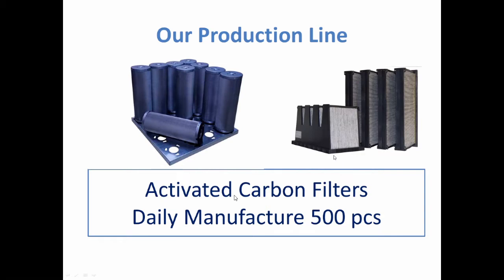The cartridge filter and the V-bank filter are used in airports, restaurants, and chemical areas. In these areas, they have air handling units, a big case with a fan inside, with pre-filter up to HEPA filter. The first stage is the pre-filter G4, then comes F7 or F8 bag filter. The third stage is the activated carbon filter. At the end, high capacity V-bank filters are used.